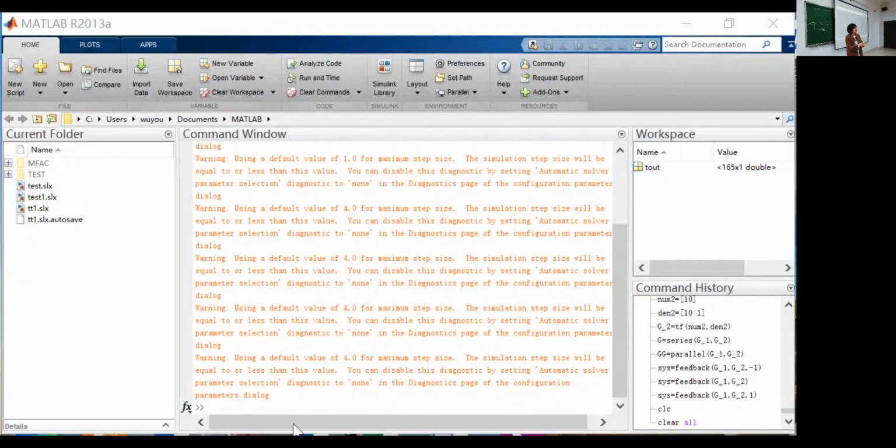But actually, each of the targets has an influence on the others. That is to say, you cannot control a system to be fast, accurate, and stable at the same time. The 3 targets affect each other. So you can ensure maybe 1 or 2 targets: maybe faster and stable but not accurate, or accurate and stable but maybe not that fast. So it depends on the system requirements.